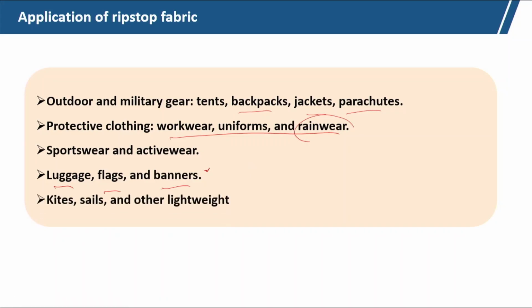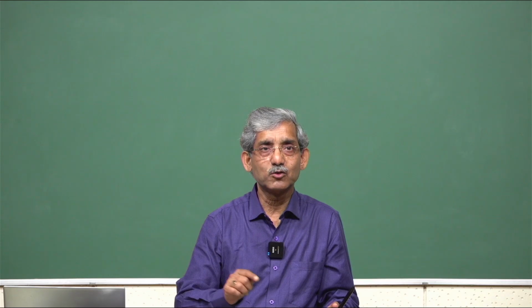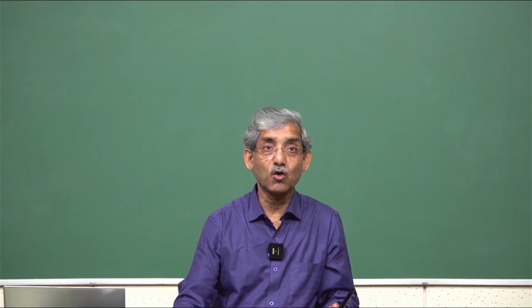Like kites, sails and other lightweight applications, where we need greater strength and less tear tendency. So, there we need this ripstop fabric in the sail. We need a lighter fabric, but at the same time there should not be tear propagation, and we need a strong fabric.